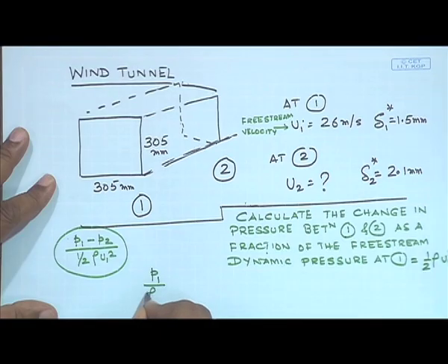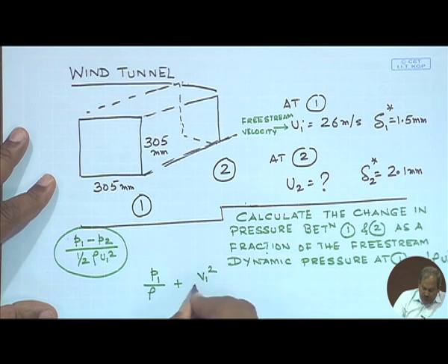So, the square area which I have right now, in which only inviscid flow takes place by the definition of displacement thickness, has a dimension equal to 305 minus 2 del 1 star on all 4 sides. And then equation of continuity can be used, Bernoulli's equation can be used, and that is what we are going to do in this problem. So, what I have in here is, then I am going to write the Bernoulli's equation between location 1 and 2.